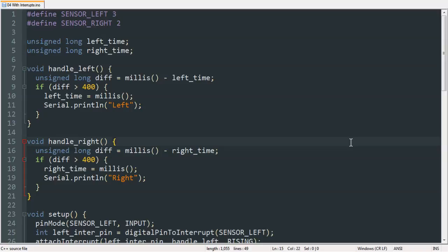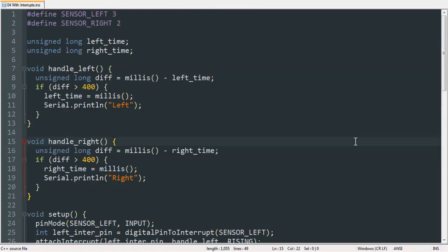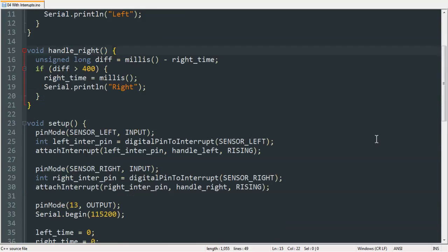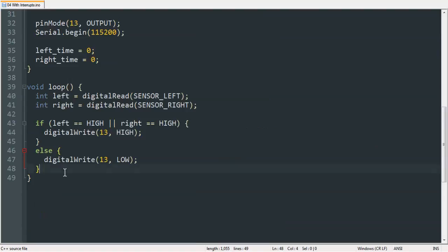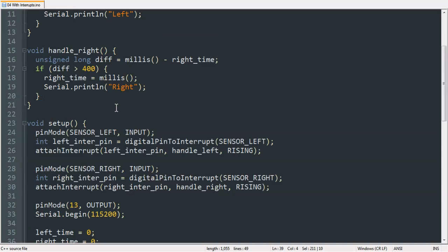Now, what we've seen so far is as far as I want to take it for this tutorial, but what I have here is an enhanced version that I will be releasing as well. This one does something a little bit differently. Instead of using our actual loop to detect when a pedal has entered the range, we're using Arduino interrupts instead. This is a slightly more advanced feature when it comes to the Arduino, and instead of having to check for ourselves when the previous state is low and the current state is high, which means the pedal has come in, we let the Arduino do it instead.